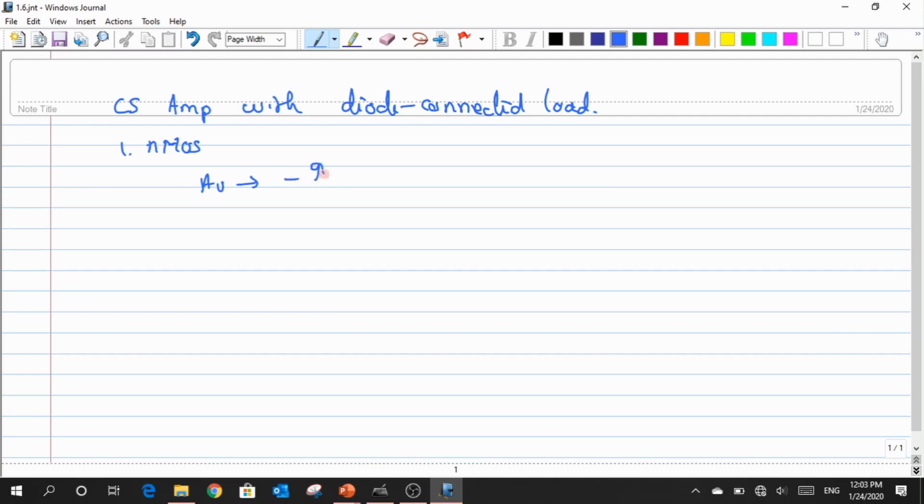So in the last class, we had discussed about this. Now in this case, first we started using an NMOS transistor. So the NMOS transistor was being used, and we found that the gain was expressed as something like minus gm1 by gm2 with some eta factor, and this eta factor was a kind of problem for us just because it introduces a nonlinearity, right? So this was introducing some sort of nonlinearity into the gain expression, and we just want to eliminate this issue.